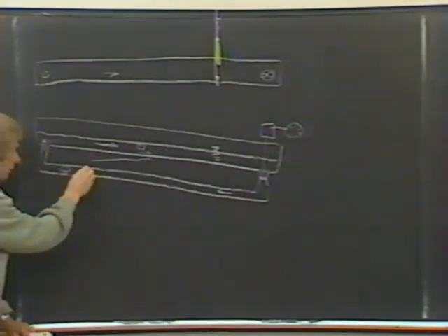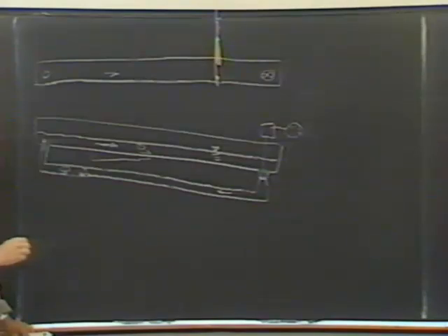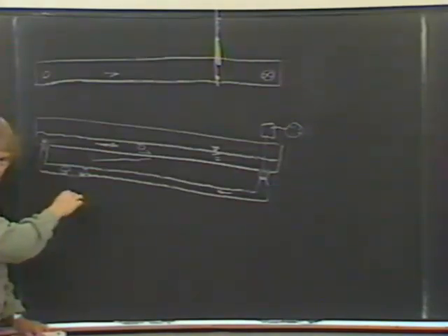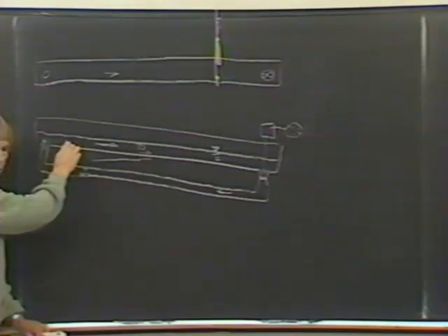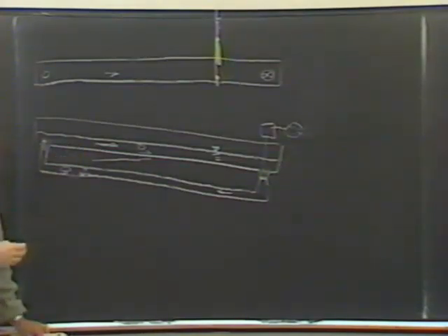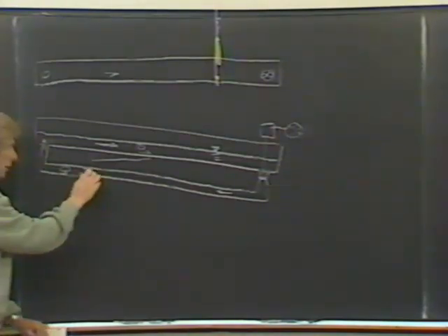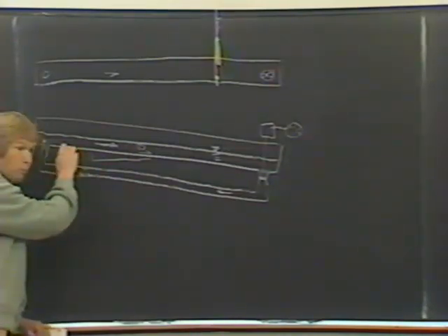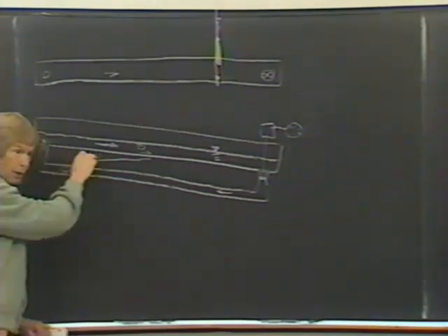The reason for that is that you want to keep the material from depositing in the return line, but you want the velocity gradients to be as close to those in the channel as you can get because of aggregation processes, that is, breakup. And you want to minimize the breakup here relative to that in the channel itself. So we have a device where we can change the slope and the velocity of the flow. We can also, of course, adjust the depth.